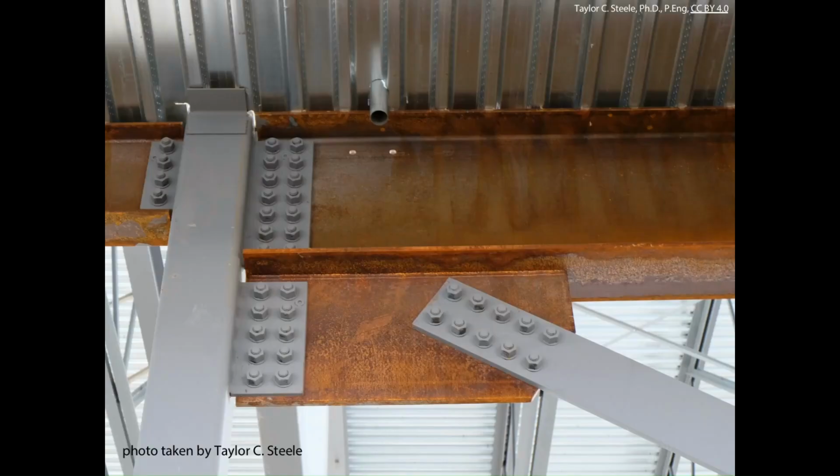I think that's 3/4 of an inch, so it might be 7/8. So oftentimes we'll bolt things. It's pretty easy to do that in the field. Other times we'll weld them. And so here's a couple of flat bars that are welded together. We'll talk more about welds and bolts later on in the course, but those are a couple ways that you can make these kinds of connections.